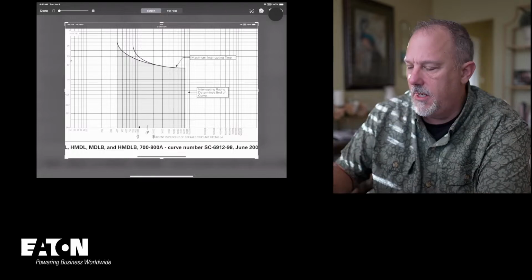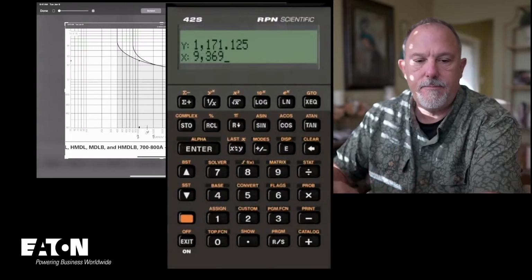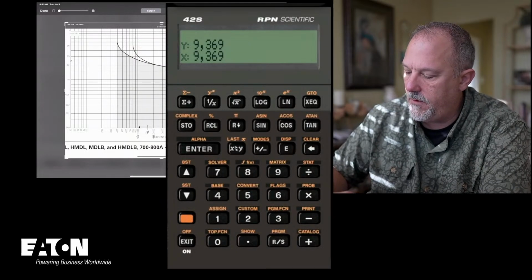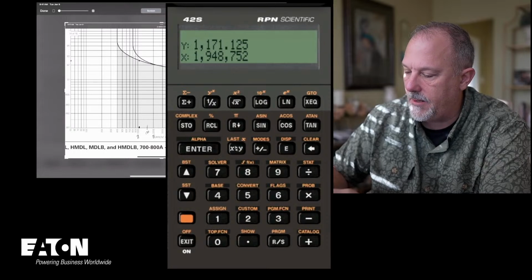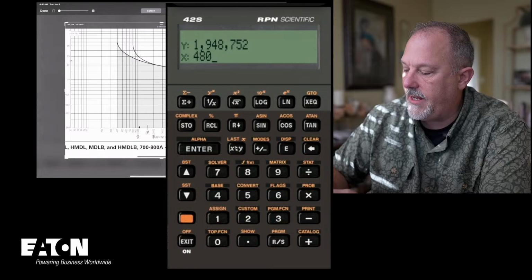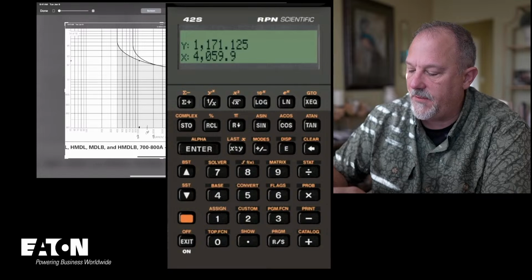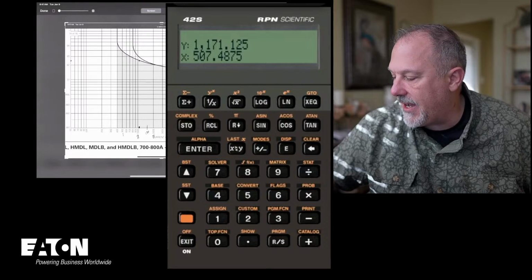I don't know if that makes sense. 9,369 amps. I'm going to do the math again. 9,369 amps, 480, 208. 208 times 480 divide. That's what I didn't do. Is 4,059. 800 divide, that's 5 times, 100 times, so I'm at 507. I didn't do the transposition. So 507, I'm down in here.